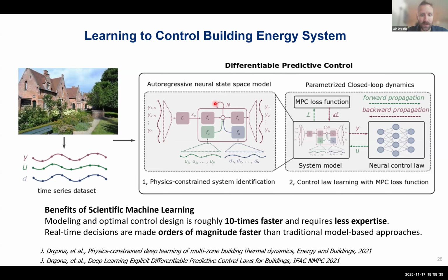In this case, we used constrained state space models, where each of the components represents a different part of the building, whether it was the thermal envelope or the HVAC system. And because we knew the physical properties, like dissipativity of our heat transfer model, we could embed these constraints as structural, domain-aware constraints that provide us with a control theoretic model that was suitable for control, at the same time expressive for learning.